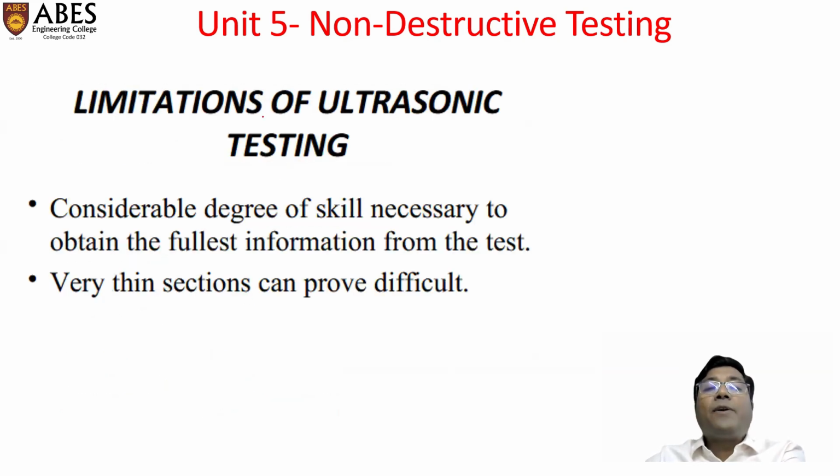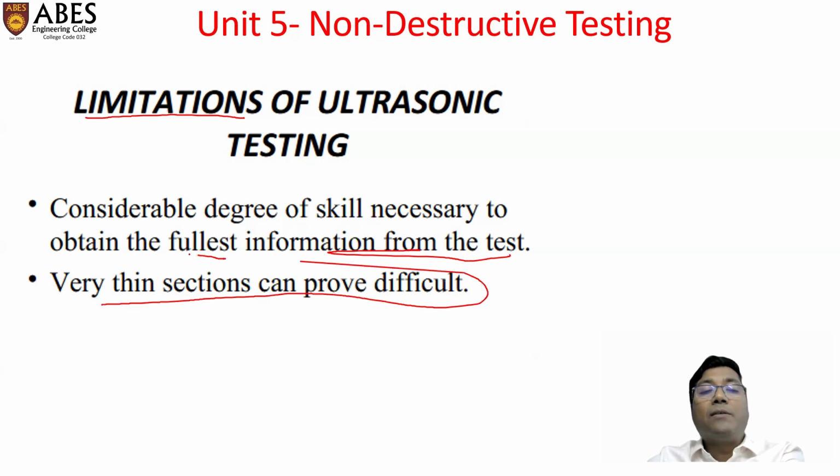What are the limitations of ultrasonic testing? A considerable degree of skill necessary to obtain the fullest information from the test would be required, and also very thin sections can prove difficult to measure, because sufficient time should be there to come back and to get back the sound waves.